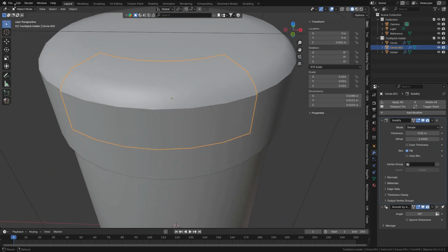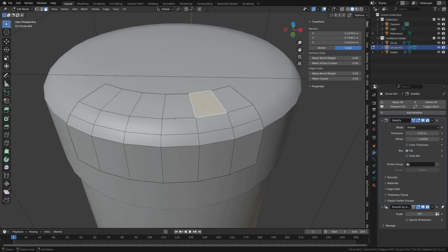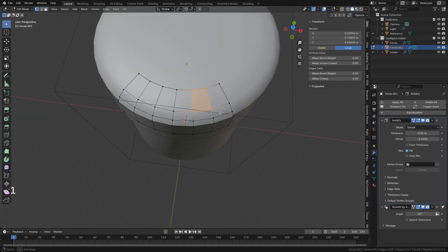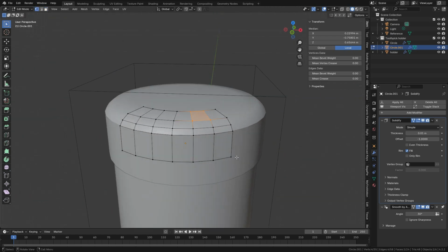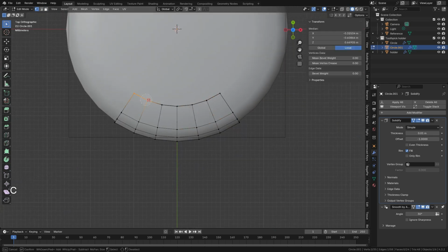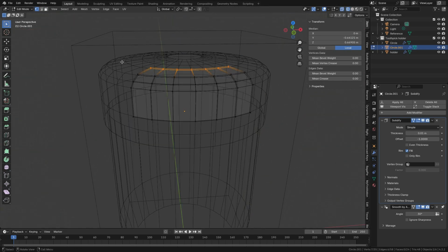So with that selected, we go to edit mode. Make sure that this triangle kind of shape is selected so you can edit the shape. Press 7, then we start working on it. So first of all, what I want to do is straighten these edges here. First of all, I like to work with half of the mesh, while the other part of the mesh is also being worked on in real time. This helps speed our workflow.